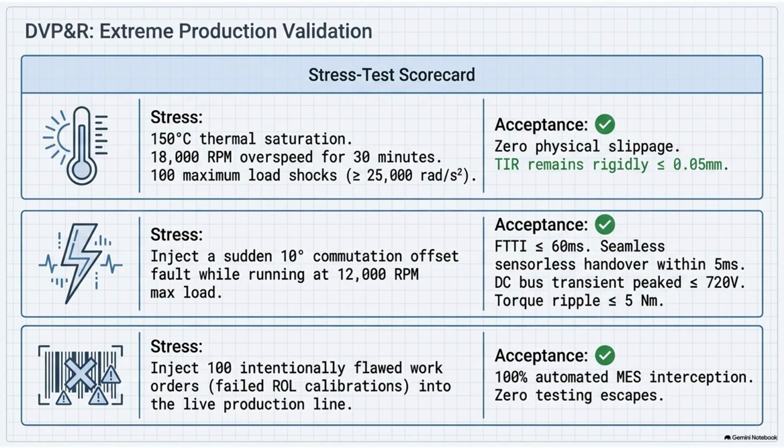Because of the aftermarket mechanic 5 years down the line, if that motor ever needs a new inverter or a software wipe years later, the mechanic's diagnostic tool needs to pull the exact original factory offset data from the cloud to calibrate the new hardware. If the data isn't there, you get commutation data loss.